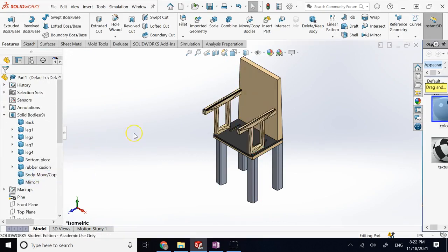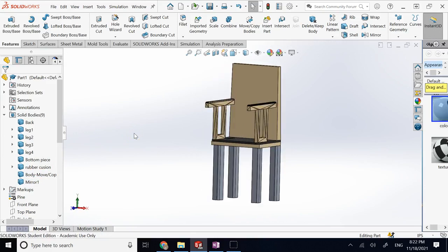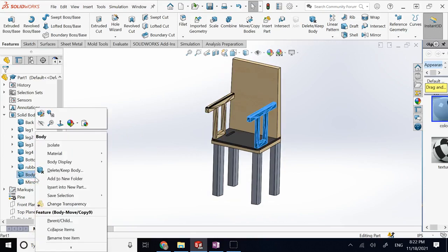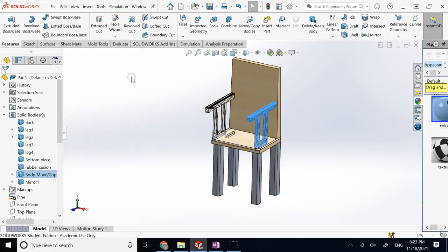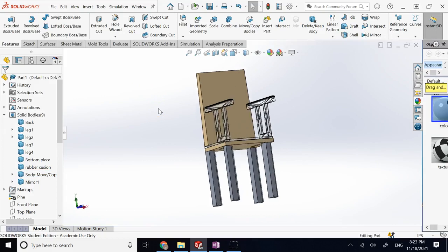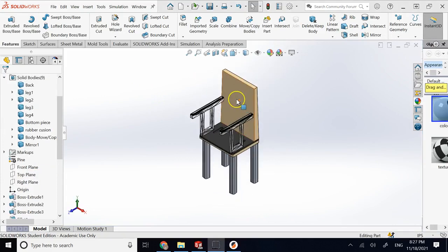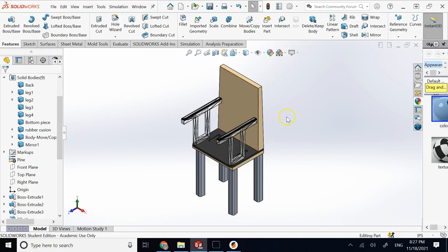So now let's say this is your multi-body object. Again, you can choose to change the material to anything you want. So let's say here I use a plastic like PC-ABS, and I have applied it to both of them because one of them is the mirror of the other one. So now let's say this is your final multi-body part, and I already saved it as chair as a SolidWorks multi-body part. But now let's say you want to convert it into STL and go and print it.